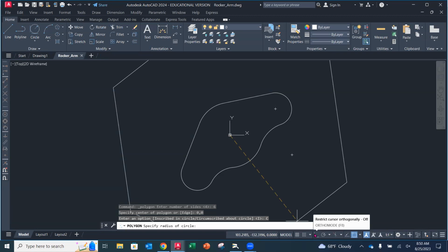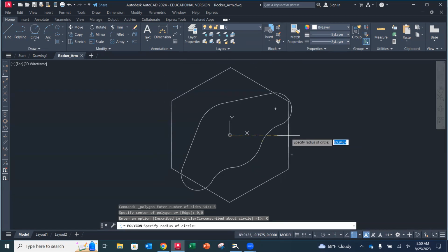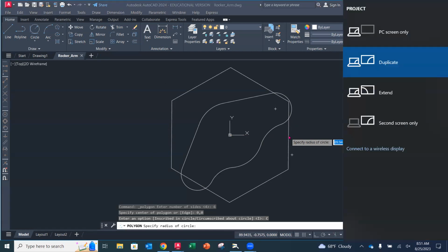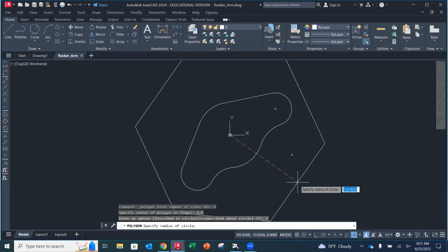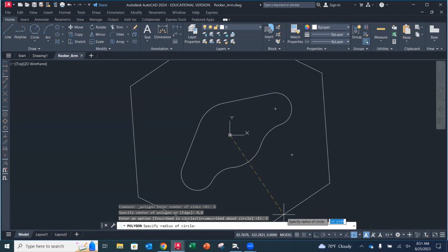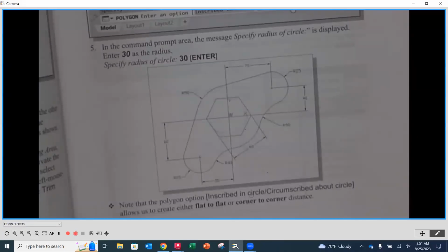Now there's 2 ways we can do it. We can either click the icon at the bottom of the screen that looks like a 90-degree angle, right? Or there's a quick command. It's called F8. When I'm connected, I can't use F8. It uses it for something else. So what I'm going to do is I'm going to click my ortho, but F8 does it if you're not connected to other stuff. Okay, now we've got to look back and we've got to get our orientation right.